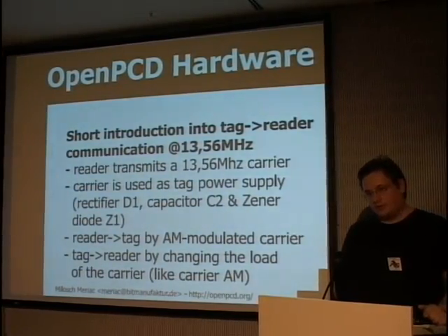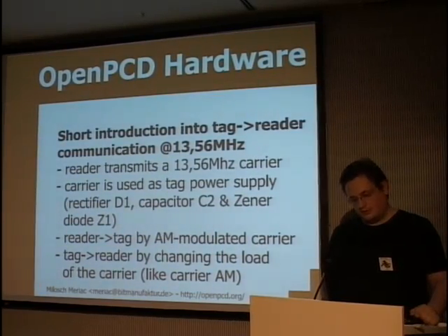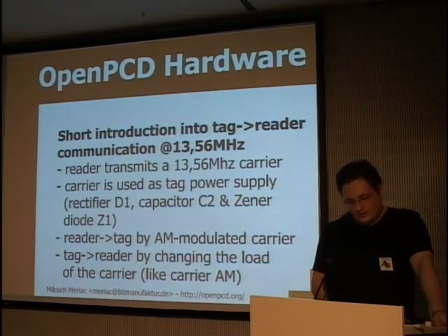Yeah, we are talking about 13.56 megahertz. This is basically the current, mostly widespread technology. It's mainly used for transportation. And the upcoming technology is this 800 to 900 megahertz stuff, but this is mostly common. There are currently nice security features already included, so if you want to use it for secure applications, then you definitely have to stick to 13.56 megahertz.